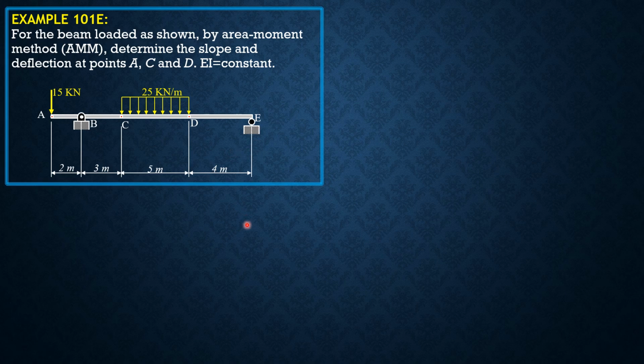Actually, if I were to solve this, I will not compute for the reactions anymore because I know the moment at E without drawing the shear and moment diagrams. Then from there, I can compute the reaction at E also. But as beginners, or those who are not yet expert on moment diagram by parts without computing for the reactions, let's just compute for the reactions.